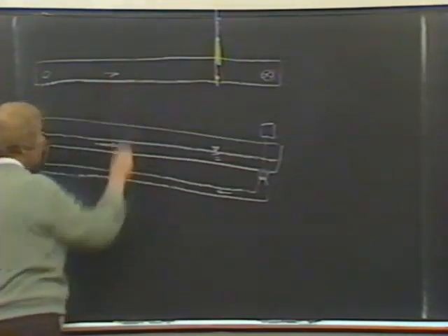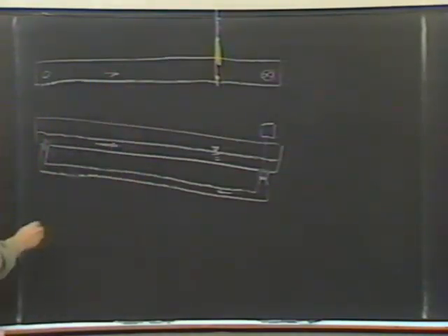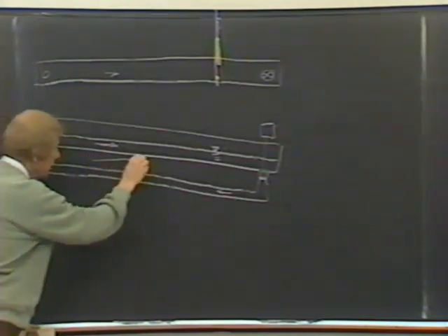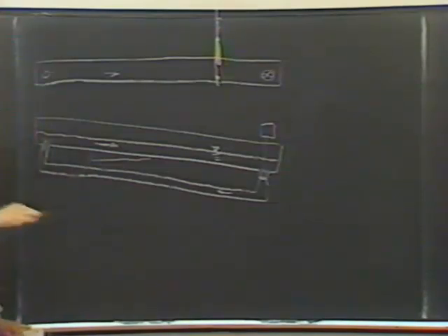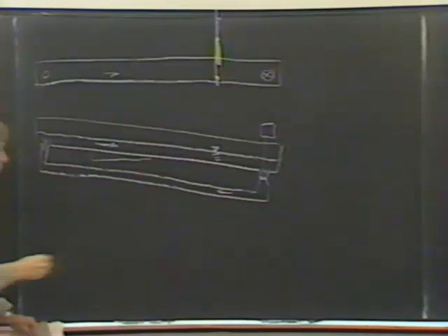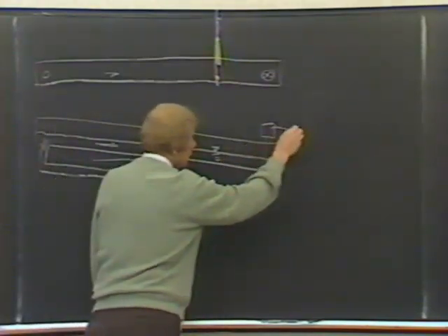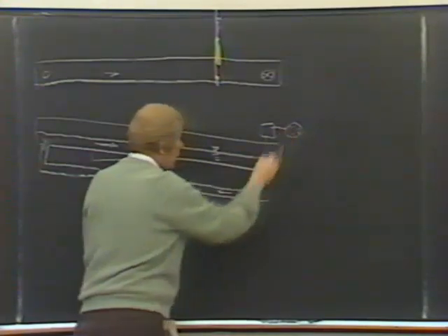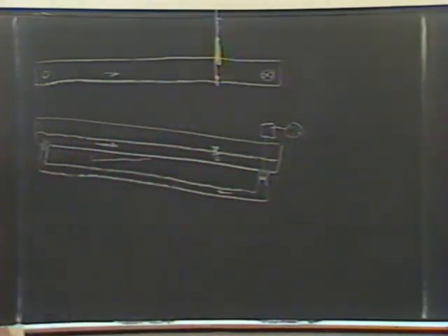The slopes are made adjustable so that you can change the velocity of flow, and the motor speed is also adjustable so that the discharge Q up the channel can be regulated.